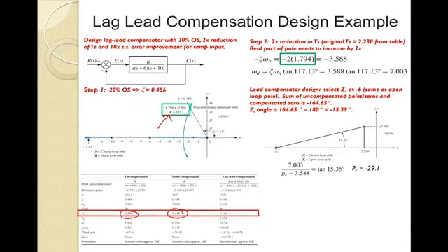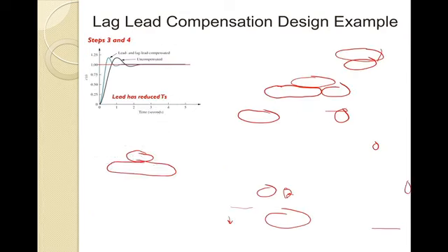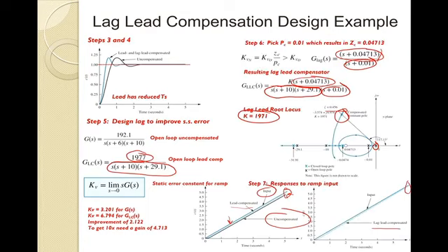So let's just go back. Again, we want a 10x improvement. And when we look at our steady state error, which is right here, due to the ramp input, for the uncompensated system we had an error of 0.312, and then for the lag-lead fully compensated system, you can see there that it is indeed a factor of 10 reduction through the design process that we had. Okay, so we basically met our goal, again maintaining our 20% overshoot when we do a step input for that system.